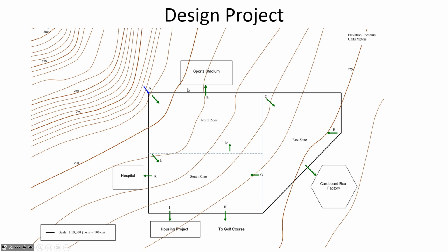So you're going to go through this process of iteratively optimizing the pipe sizes, which means you're going to be changing the pipe diameters over and over and over to try and find out what's the smallest pipe size that you can get away with at each of the sections in the network to provide the minimum pressure under the demand condition of maximum flows. So that's one side of your design optimization: you have to have at least a minimum pressure on the day where it's really hot, so everybody's using a lot of water.